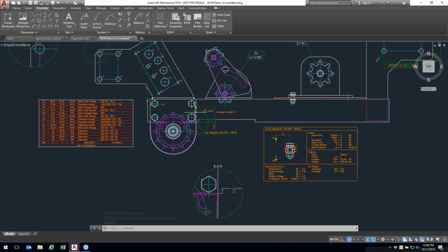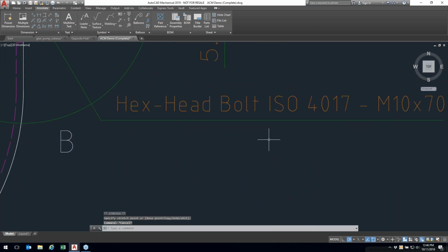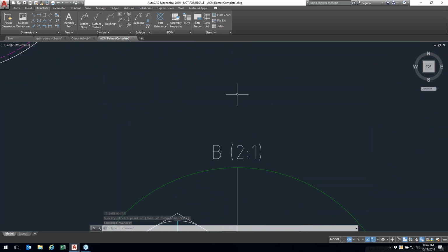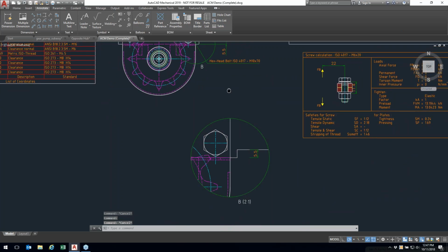But once you have a detail view defined, if you go into AM Power Edit, you can select that detail ring, and then it will redefine the geometry. And the idea is it was also giving me the chance to potentially add the note or the connection line at that point. Some other things, obviously in this case, that detail ring will auto move around. The text is always attached to the ring itself. So as I grab that and move it, it'll just stay in position around the ring.